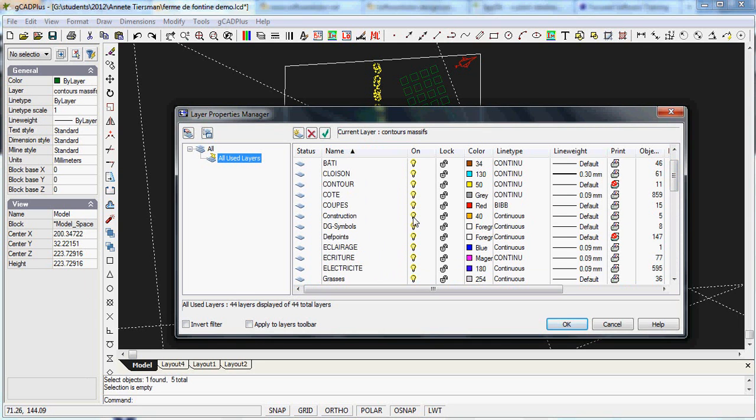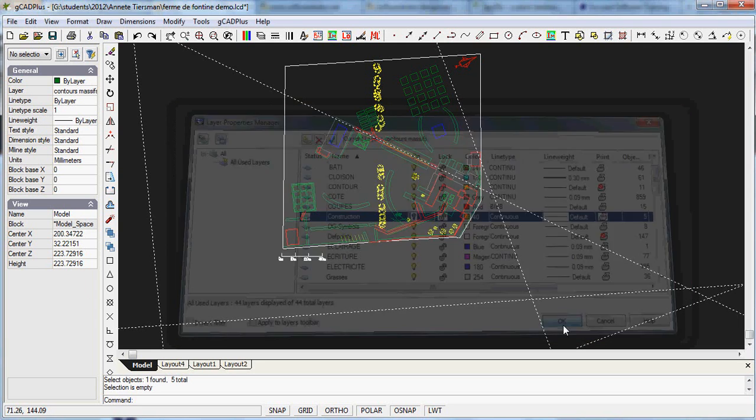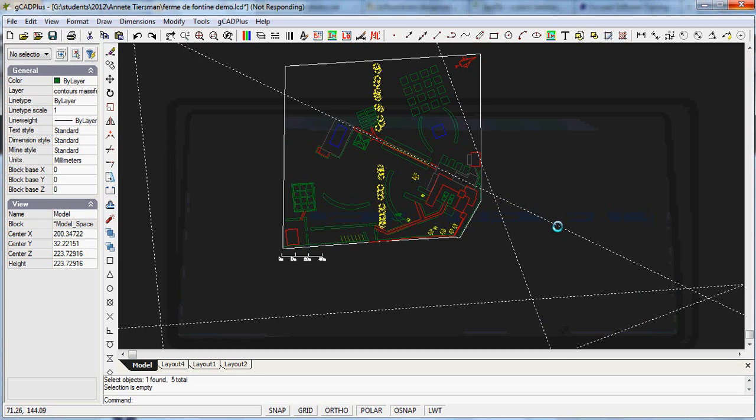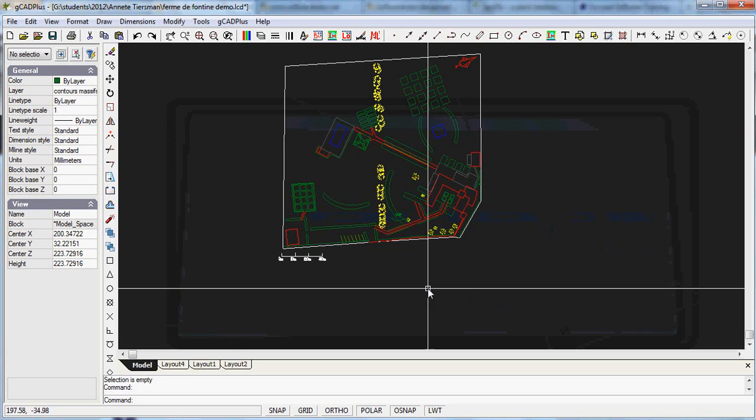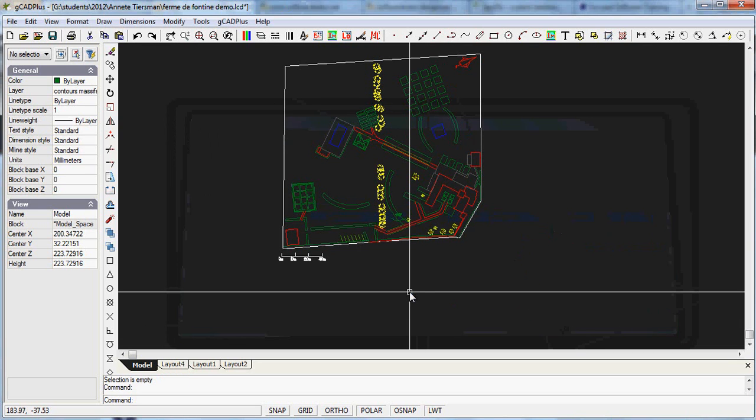So what I want to do now is just turn off the construction lines here, and after the drawing regenerates, those lines should no longer be visible, and so that when we go to plot and print and form a layout of this, they won't bother us. But they're crucially important. You just need to be able to turn them on or off at will.